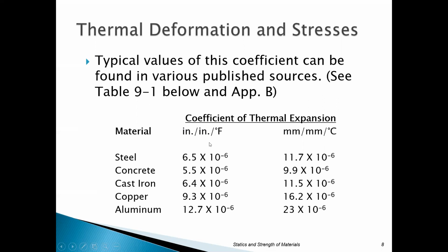Okay. So that's pretty important, particularly if the problem doesn't give you the number. It just says, hey, you've got a temperature change of so many degrees. You have to go look that up, and make sure that you get the right one. You'll memorize some of these maybe if you're doing them enough. I use this one out in the field all the time for steel because that's important if you're doing temperature changes for measurement. Concrete's another pretty common one. These are easy lookups, but just make sure you're getting the right one: centigrade with the centigrade problem and Fahrenheit with a Fahrenheit problem. Okay.